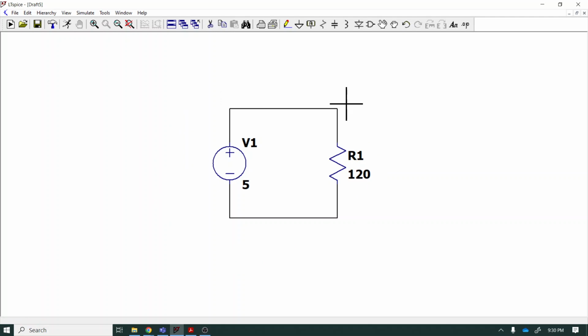One thing that we need to do in order to do the simulation is we do need to put in a ground connection. Now, you can build a circuit like this with just a battery as your voltage source and a resistor and not connect it to ground, and the thing will run fine. The physics of this doesn't require a ground connection, but the actual simulation itself requires you to define at least one point in the circuit to be 0 volts that everything else can be measured in reference to. So we do that with this little button here. The little down arrow specifies ground.